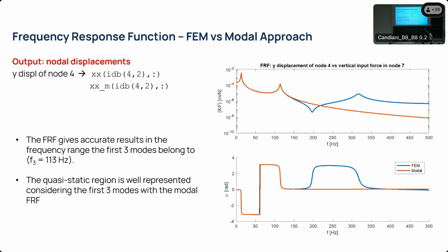In this case, remember, we are trying to get the response between an input at mid-span and an output at node 4, so roughly at quarter span, but only considering the first three mode shapes. And if you look at it, we are missing all the mode shapes after the third, because we decided to use only some of them, so we discarded all the ones at higher frequency. And so, due to our simplification, due to our discretization, we cut out all the contribution at higher frequency.